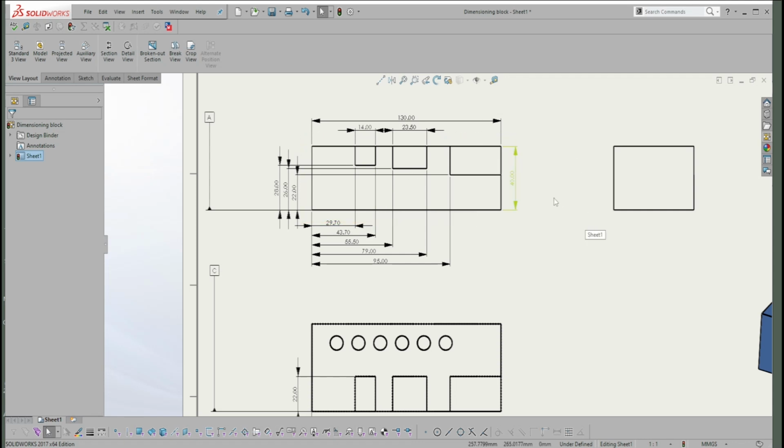for us. All I want is that every feature that you have, and you're going to have to identify what are features and which are not. But then it's not that difficult. Every feature just has to have at least 2 position dimensions, and sometimes it's inferred. So the position dimension won't always be an actual dimension. It'll be something you infer, which we'll get to. And then it has to have at least 2 size dimensions.